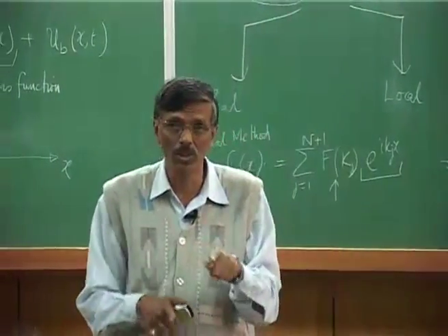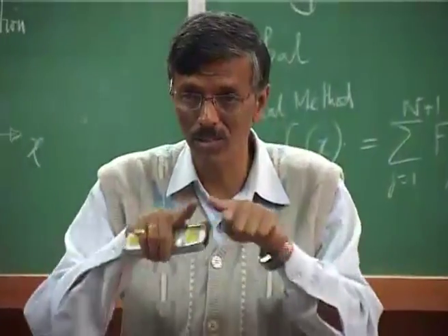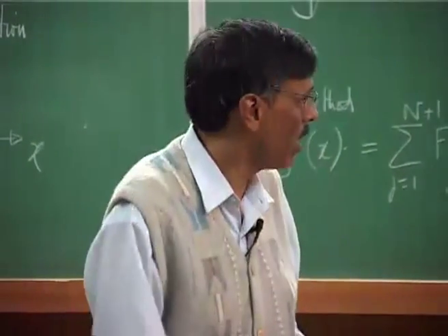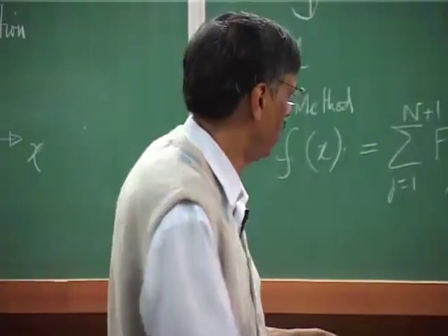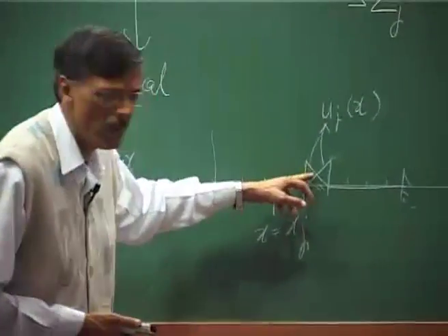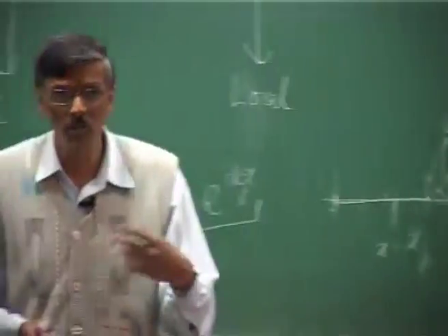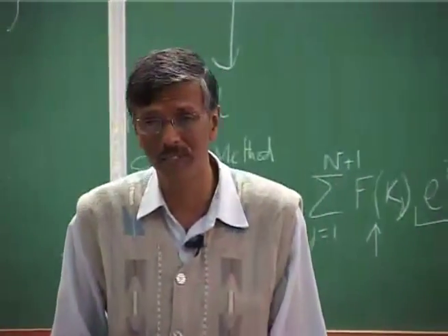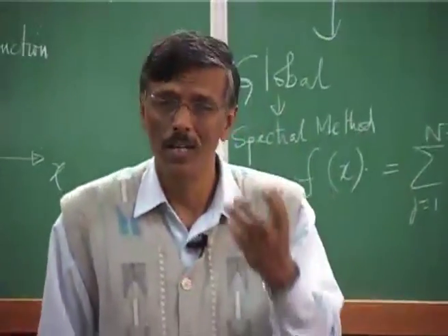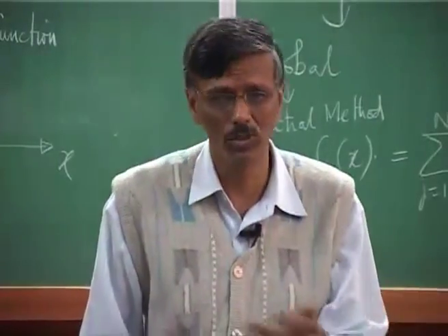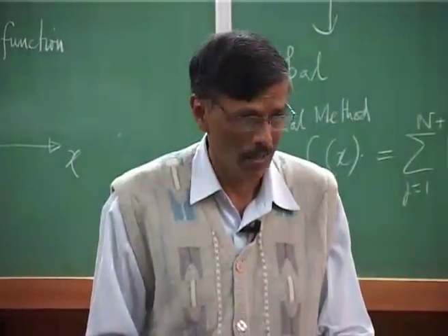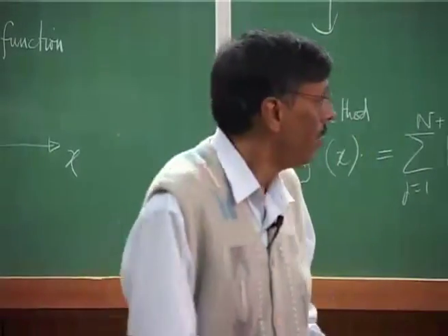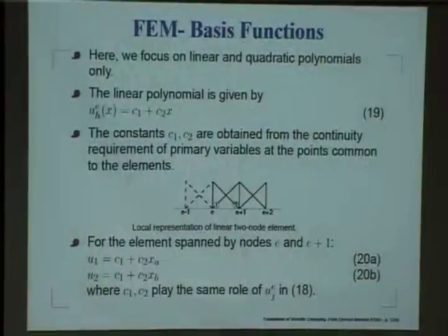Even though I am talking about a linear variation in x, I still should be able to compute a solution where at the element level the solution may be continuous. That is what it means, that it must be complete. So, whatever may be the order, I may decide to take a cubic polynomial here, that would still give us the flexibility to satisfy any functional variation which could be maybe a constant, which could be linear or a quadratic, but it would surely be able to do that.